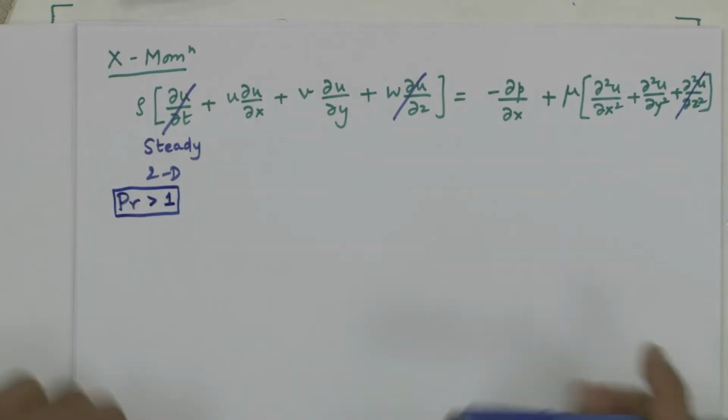See, what is my idea? My idea is to solve for velocities and the pressure. That is what the momentum equation is going to give you. 3 momentum equations, x, y, z. Pressure is the unknown, and the continuity equation is there. So, 4 equations, 4 unknowns, things are solvable. A crude way would be to solve the entire set of Navier-Stokes equations, x momentum, y momentum, z momentum, over the entire flow field and not bother about anything. Okay, that is not the smart way of doing it.